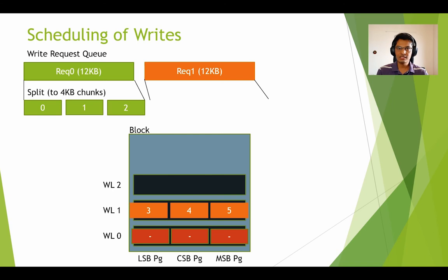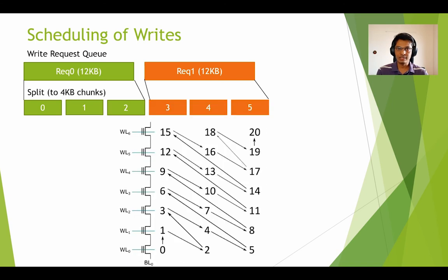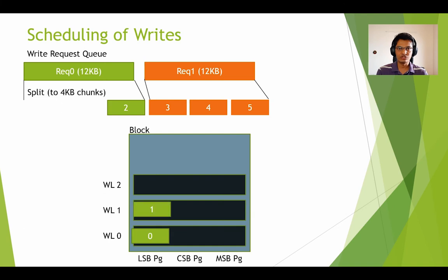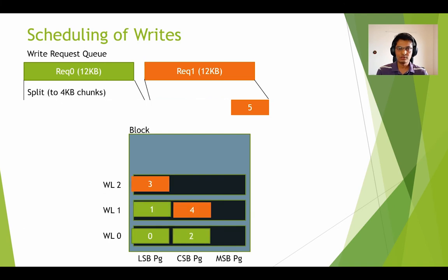To prevent this, pages are programmed in shadow programming sequence, which is the zigzag pattern of writing data into the block. However, this process of programming may prevent data requested later during the read operation from being in the same melded page. Now, reading the entire melded page when only a part of it is used to fulfill the read request has a negative impact on the read performance.